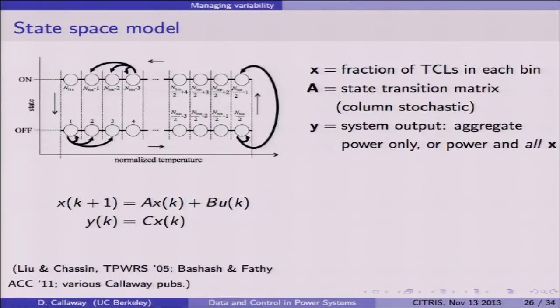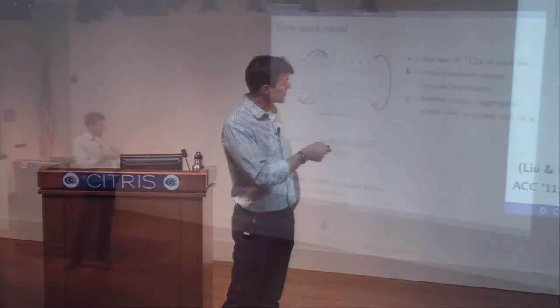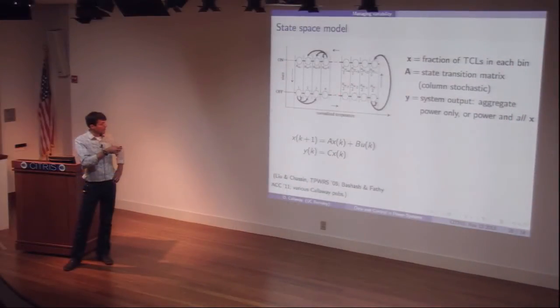Yeah, question? I mean the actual temperature. So the idea would be that a set point, most thermostats operate with something like a 0.5 degree Celsius deadband. And so this would be the temperature within that 0.5 degree Celsius deadband. So it's a relatively small distribution of temperatures.